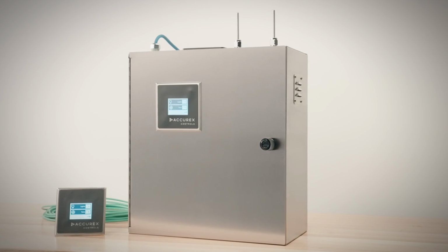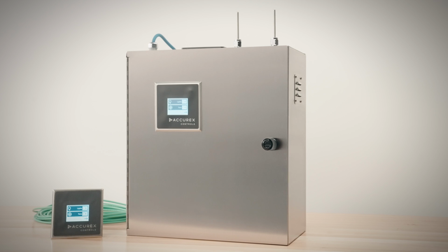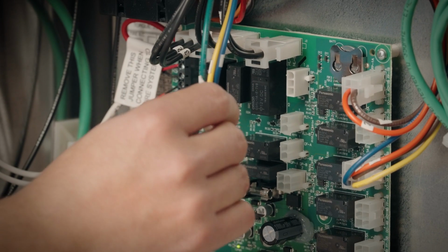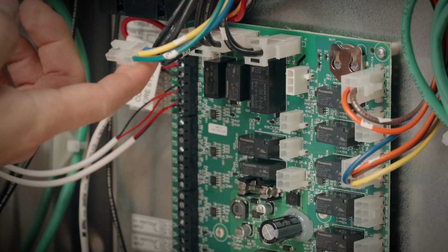The temperature fault condition puts the board into temperature interlock mode, putting the fans into automatic operation. To regain control of the fans, either cycle power to the controls or wait for the temperature interlock to expire.